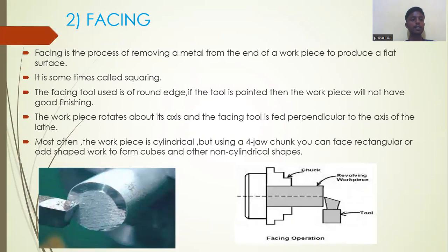Facing. Facing is a process of removing metal from the end of a workpiece to produce a flat surface. It is sometimes called squaring. The facing tool used is of round edge. If the tool is pointed, then the workpiece will not have good finishing.